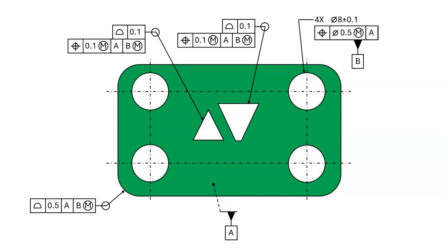Today I'm going to talk about how we can use simultaneous requirements to help us with our designs. A simultaneous requirement is when multiple feature control frames have the same datum references in the same order with the same modifiers. Here, the feature control frames that reference A primary and B at max material boundary secondary are simultaneous requirements. When multiple feature control frames are a simultaneous requirement, there is no datum feature shift between those features. We will see why that is and how we can use it to our advantage to accomplish our design goals.